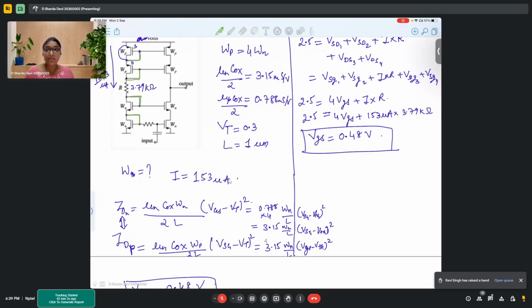In cases where the PMOS or any of the NMOS have a different W in series, the scenario would be different, right? One thing is for sure: all the transistors will carry the same current. So let's say your W is changing. For one PMOS it is something, for another PMOS it is something else, so depending on that, your values will also change.